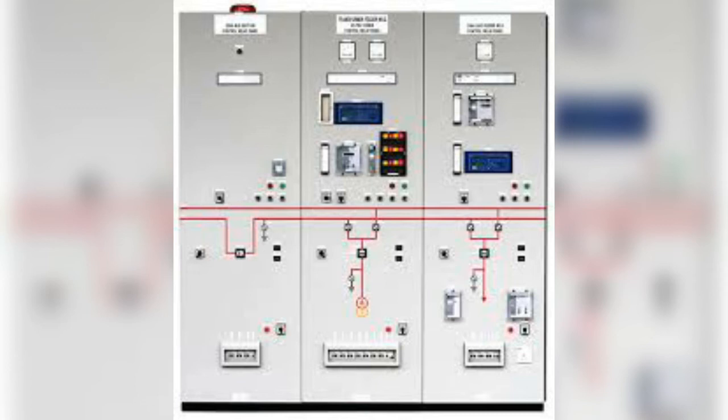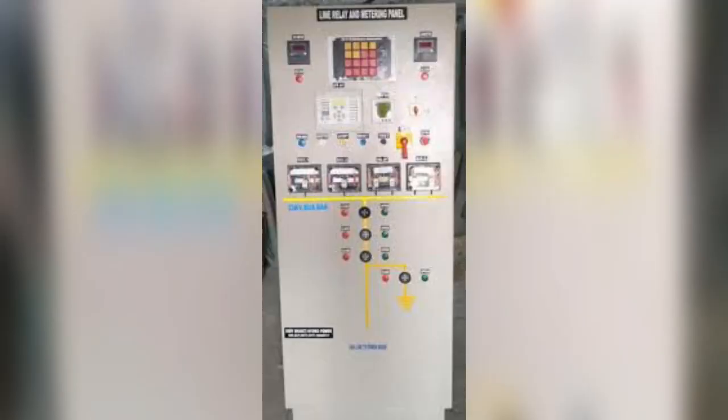It means if the prime mover does not supply the proper RPM to the alternator, then the alternator will be at under frequency or low voltage. It can be caused by a governing fault or auto governing fault in a steam or diesel generator. Mainly the diesel generator behaves like this.